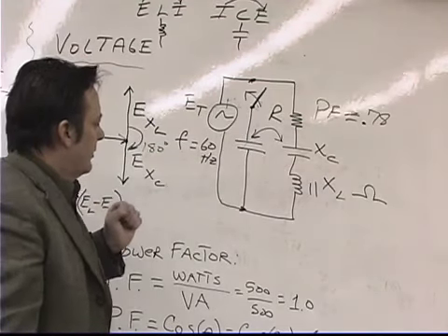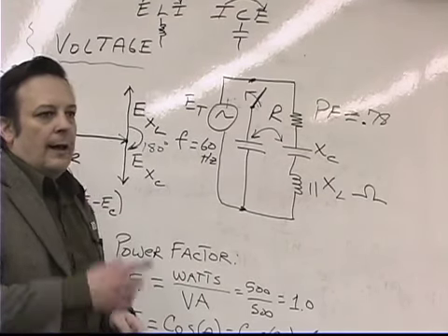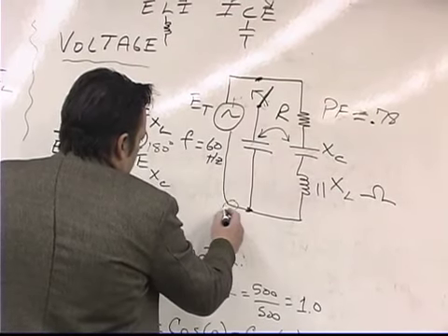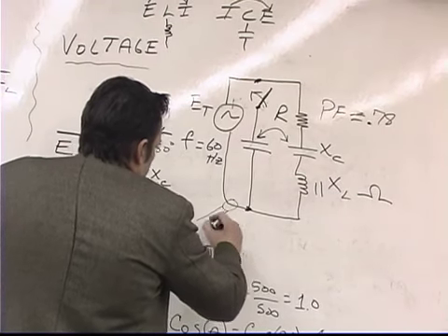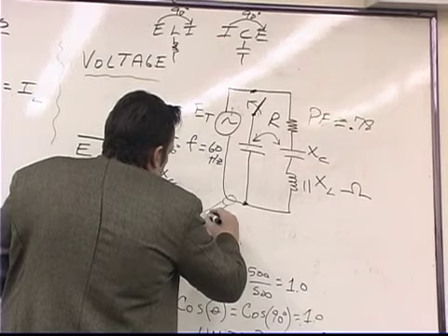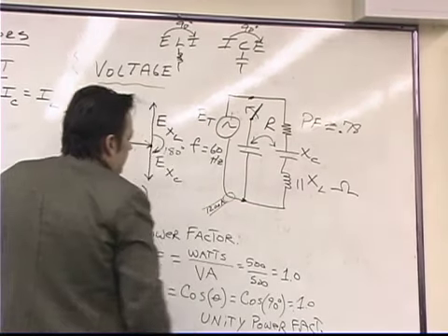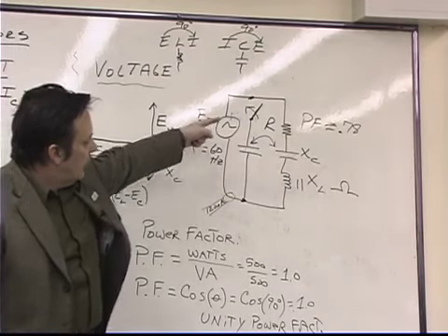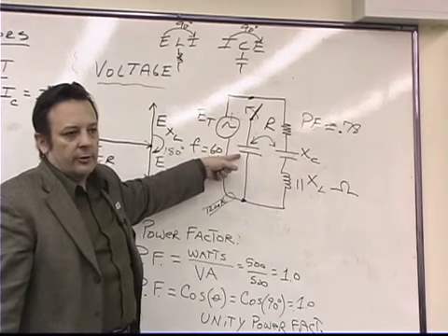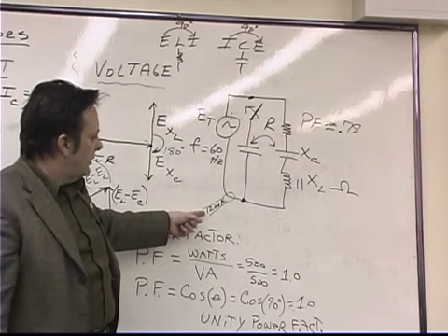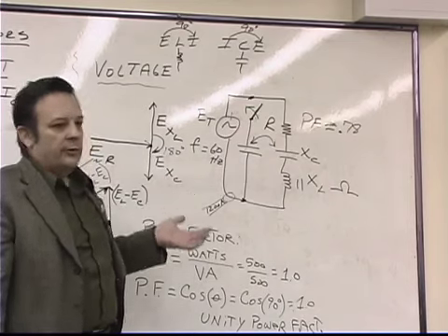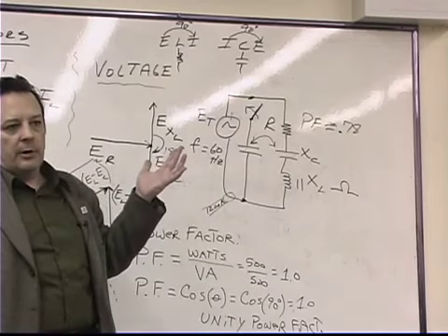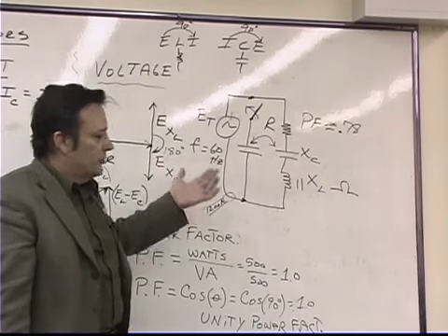And so what I've done on several occasions is take a clamp-on Hall effect ammeter, which is a meter that just clamps onto the cable down here and then displays current. So let's say that this was drawing 1,200 amps. We clamped a meter onto this cable when the capacitor was not inserted into the circuit, and we saw that the power factor was 0.78, and the current we were drawing from Diablo nuclear power plant or whatever source we were using was 1,200 amps.